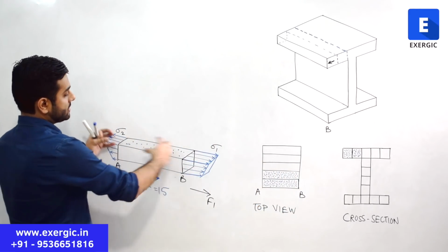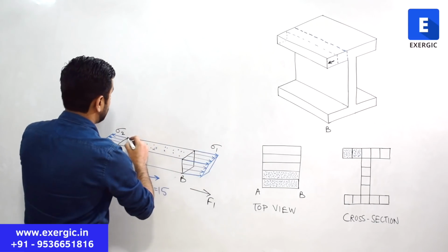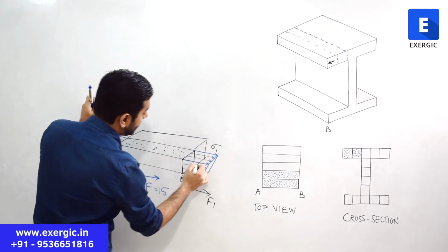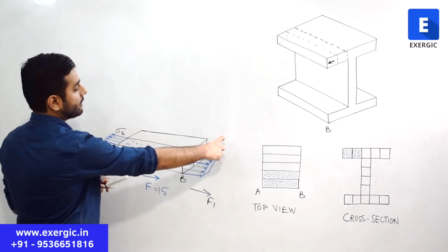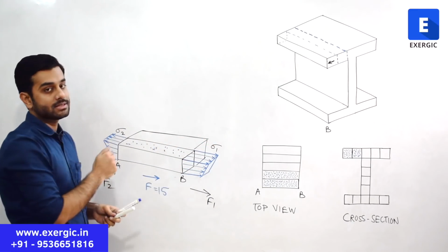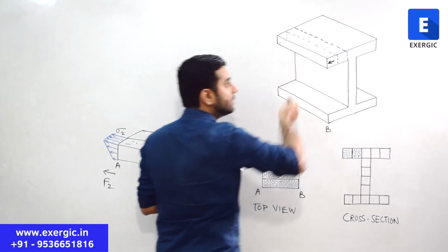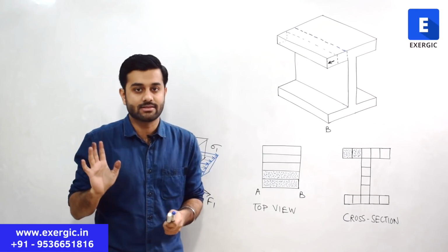And here, just like we are having one cuboid, another cuboid will be added. The same exact dimensions will be replicated, will be doubled. And now tell me what is going to happen. Sigma 1 will be present there also, sigma 2 will be present here also. With the width of the beam, we are not considering any change of the stresses, of the normal stresses, right?